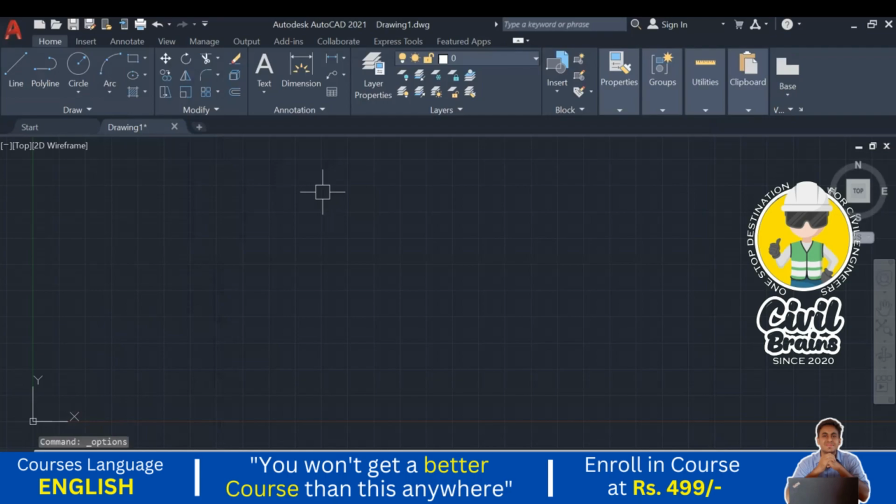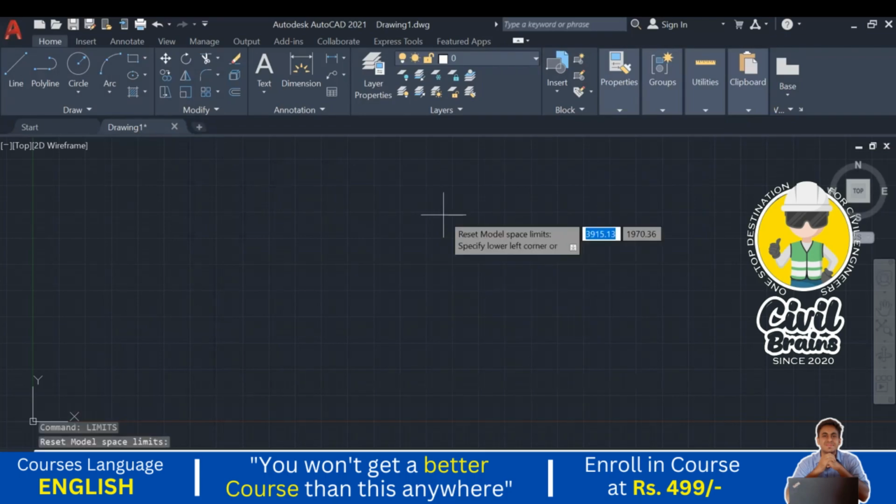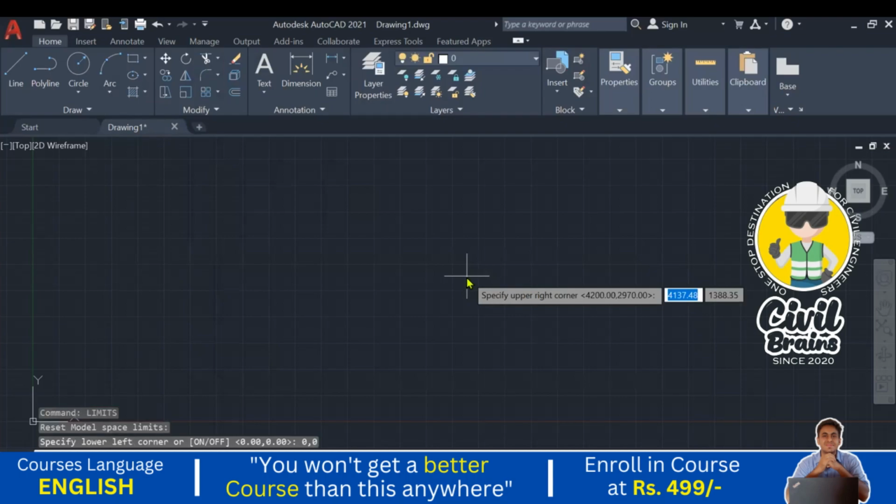Okay, so here we are changing the limits. I just type limits, press enter again, 0, 0, press enter. So I go here in our plan. Here you can see this one is 7,000 by 3,500. We just want a higher one, so I just consider 10,000 here.